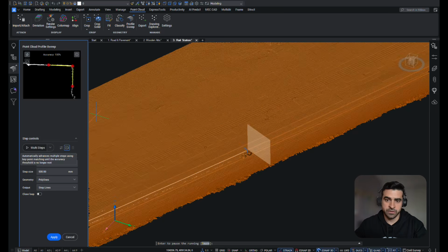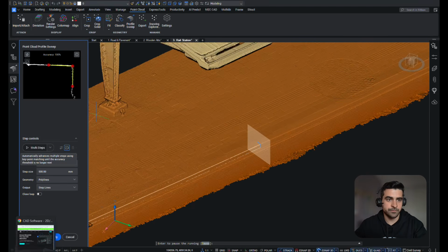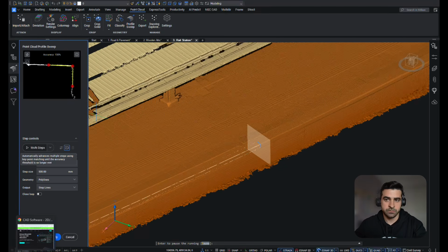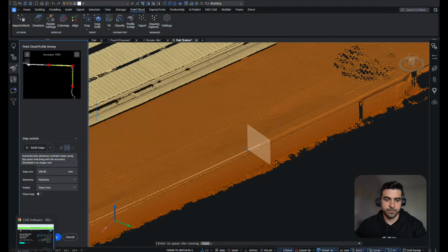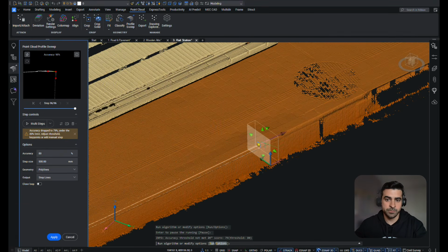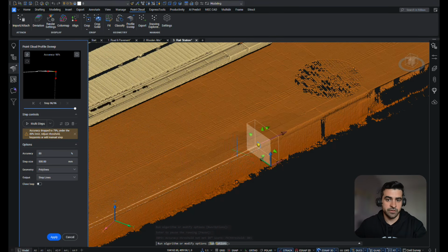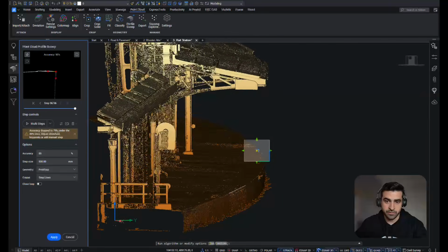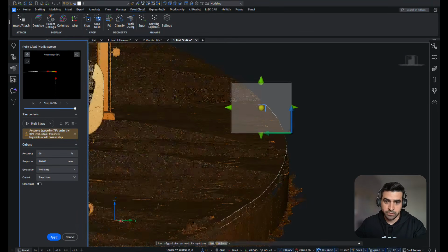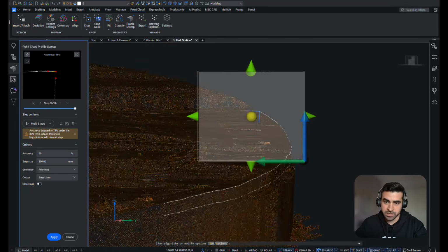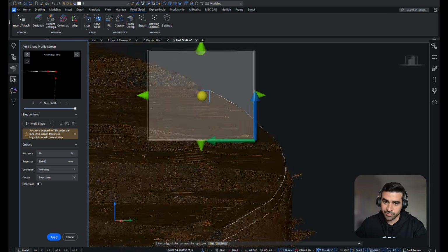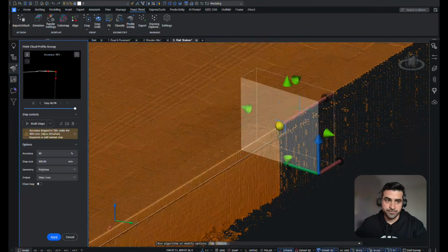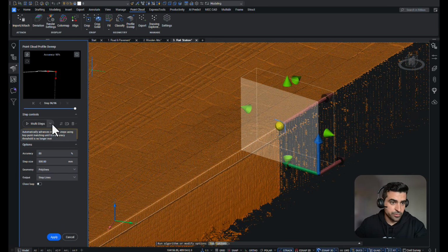Okay, no significant deviations so far from the accuracy point. Okay, and now it stops because clearly the accuracy fell under the 80% mark. But we can already see that the break lines have been created in a very, very precise manner. So what can we do in this case? The precision stopped, so I'm repeating the same process.